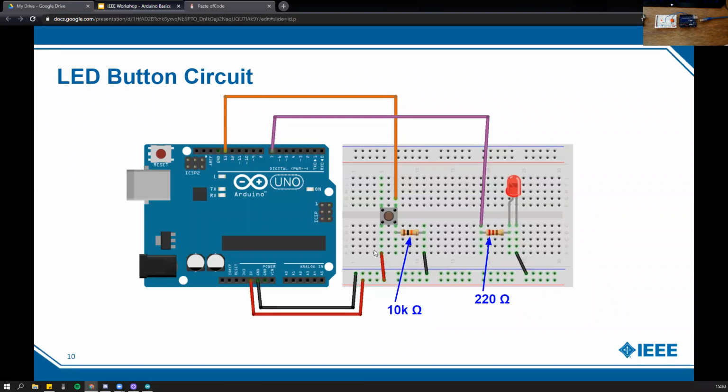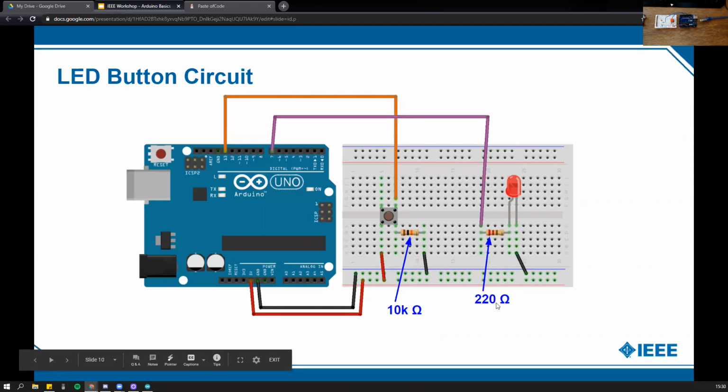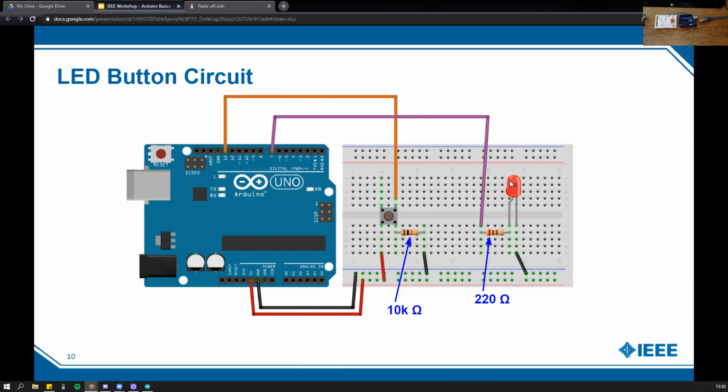And when there is a high, it will let it go up to the value so that the Arduino can detect that it's a high. And then afterwards, the Arduino will send a signal to this LED. There is this resistor right here just to limit the current, and then it goes to ground. And the Arduino is supplying the voltage and the ground right here.